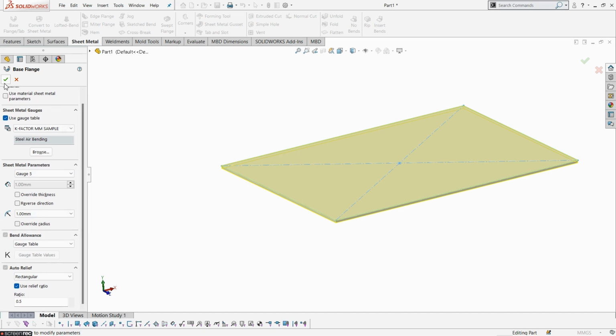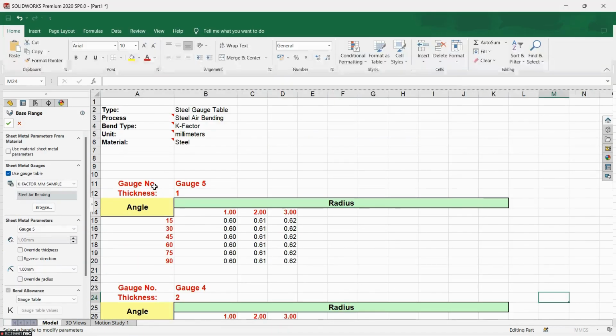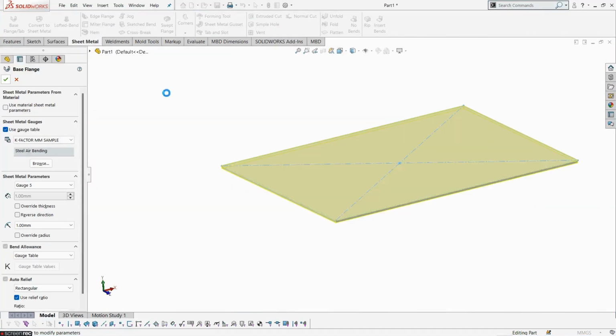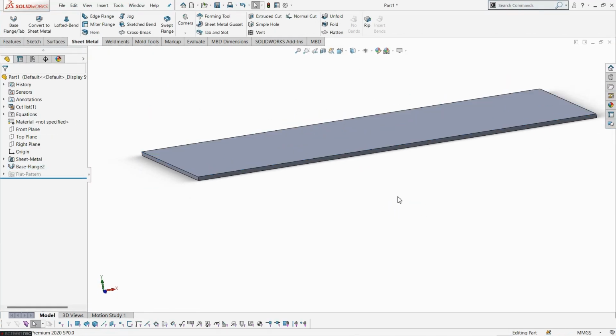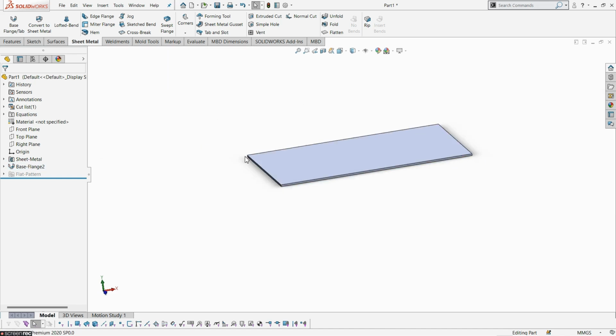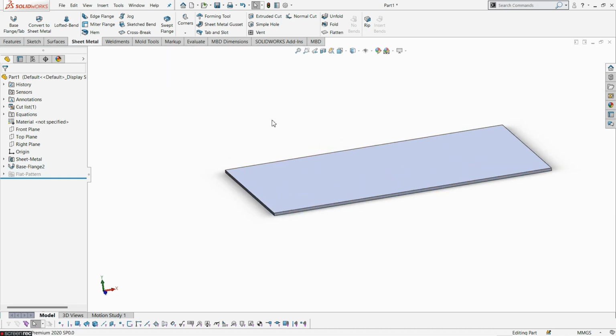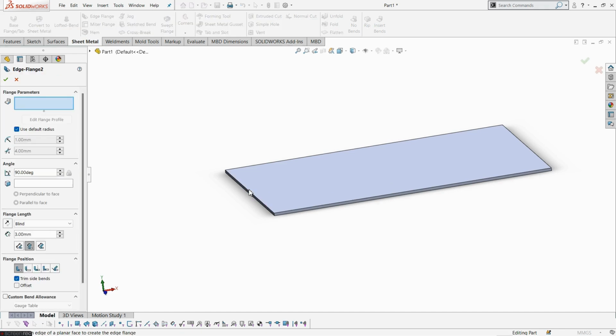Always maintain the K factor ratio at 0.5, because if the ratio is 0.5 it doesn't affect your sheet metal and the overall thickness of that particular part. Because if you apply any kind of pressure or make a bend in the sections, it is not affected if you know the K factor. Because different materials have different kinds of factors, you need to consider it.